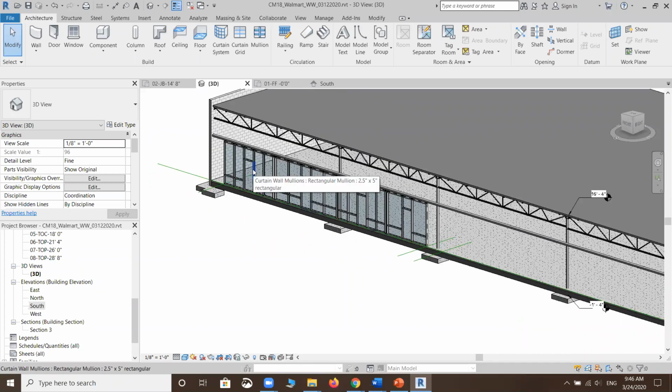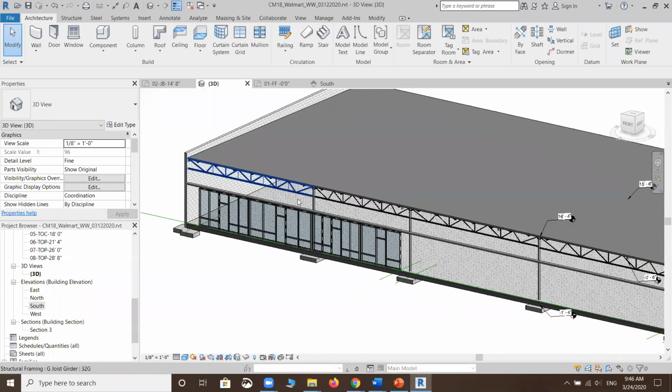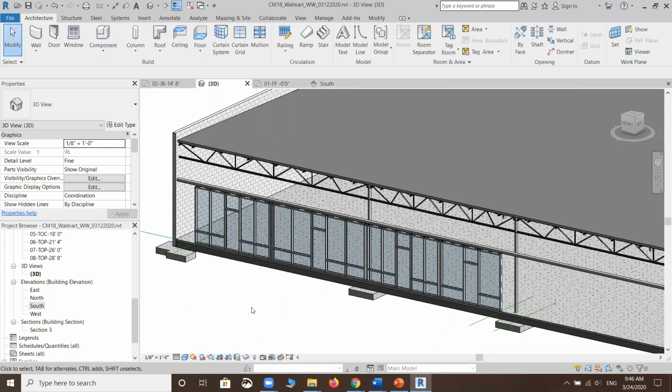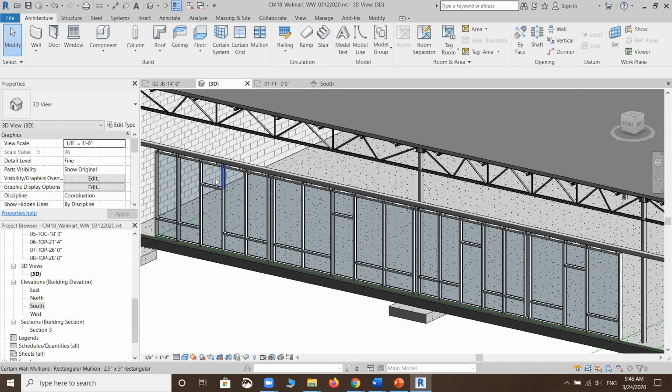But at this point in time, take a look at your current wall system you have done so far, and try to figure out, do you recall all the steps we go through? How do we actually determine locations of the curtain grid, and how do we utilize the door location to determine the separation of those small panels? How do we apply the bottom curtain grid? How do we apply the top curtain grid? And how do we add or remove segments on the same curtain grid? Those are the little techniques you have learned so far in this session.